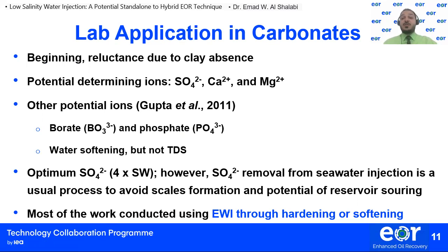However, here I need to stress that we need to be careful with the use of sulfate ions, because that usually will cause scale formation and potential reservoir souring in our reservoirs. So I need to highlight that mainly the efforts in carbonates were concentrated on engineered water injection, which is ion manipulation through softening or spiking of some of those ions.